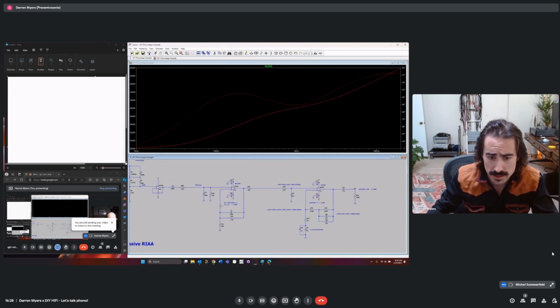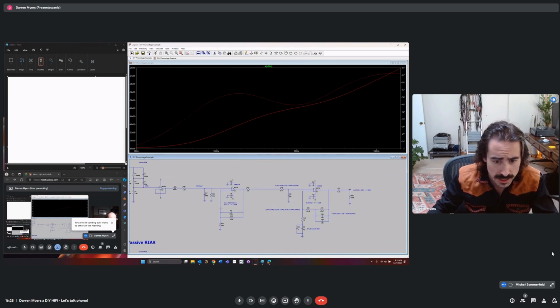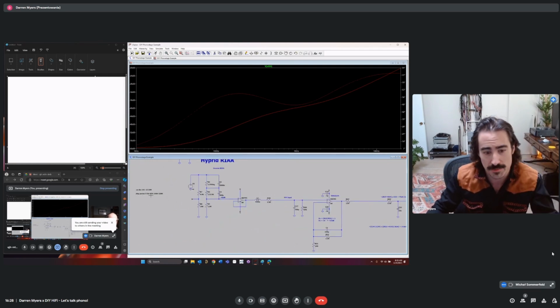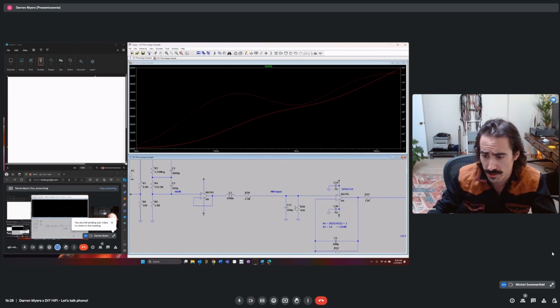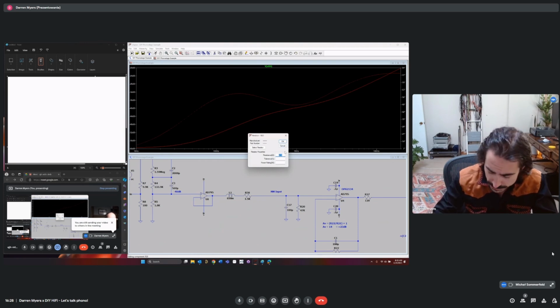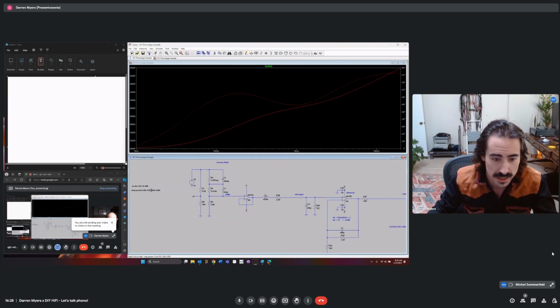Now I'm going to use, this is a bit more advanced, the step param feature, which is going to step out various different loading resistors. We can do this with our capacitor too. It's going to run simulations on anything we put in this list, and you can make this list as long as you want.